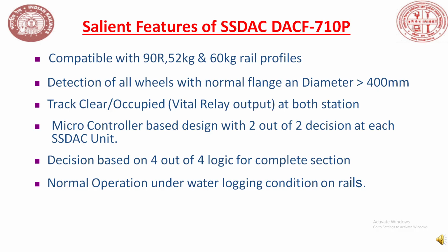Compatible with 90 or 52 kg and 60 kg rail profiles. Detection of all wheels with normal flange and diameter more than 400 mm. Track clear occupied vital relay output at both stations. Microcontroller based design with 2 out of 2 detection at each SSDSC unit. Decision based on 4 out of 4 logic for complete section. Normal operation under water logging condition on rail.